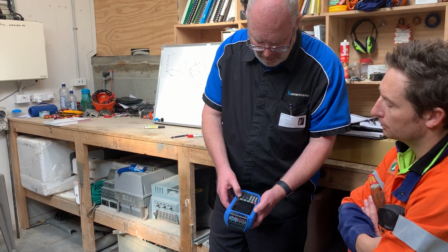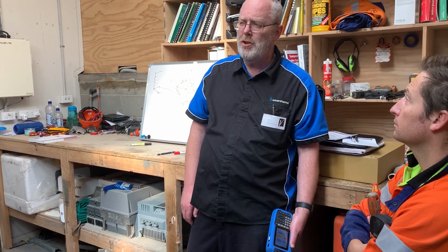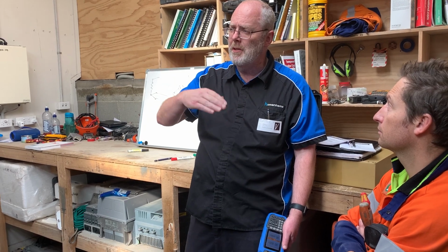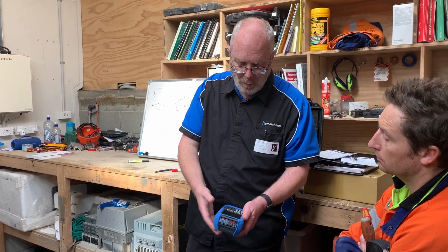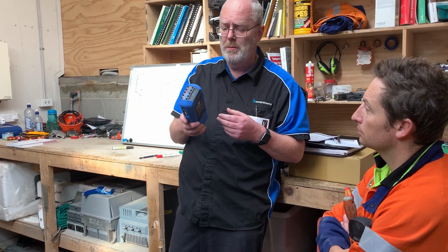If you go to ohms, you might have some old-fashioned things, the Honeywell pressure trolls, remember those? They have a pot that goes from 0 to 400 ohms. A lot of automotive stuff has potentiometers 0 to 400. So again, you can simulate that or measure it. Okay, cool. It is a beast. You'll be so delighted you bought that.